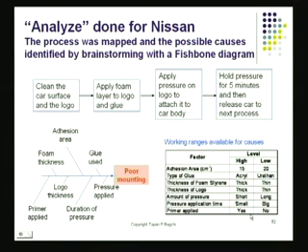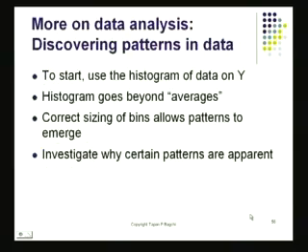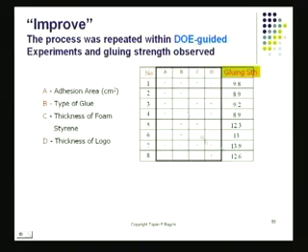Once I do that, it becomes very easy for me to show that on my matrix. So the first experiment will be done like this: factor A set at plus level, factor B at plus level, factor C at plus level, factor D at minus level. I run the process and check out the resulting gluing strength, and this is actually the sum of two strengths.